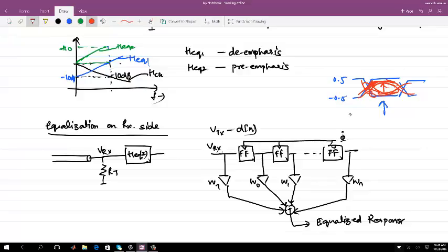It can be higher or lower. And ideally what we want is to pass the same voltage on the next clock edge. So the flip-flop which was operating on a fixed signal swing now has to operate on more or less an analog signal. So that is the difference which will come now.